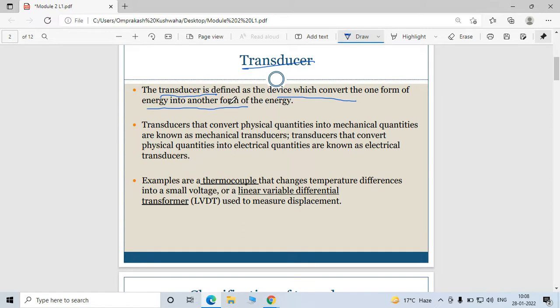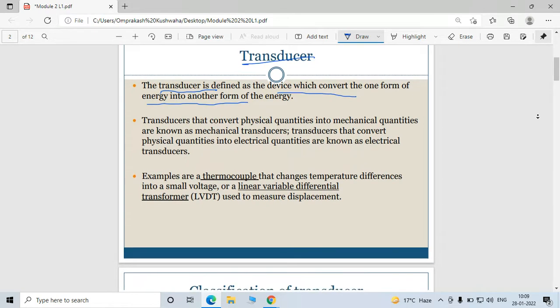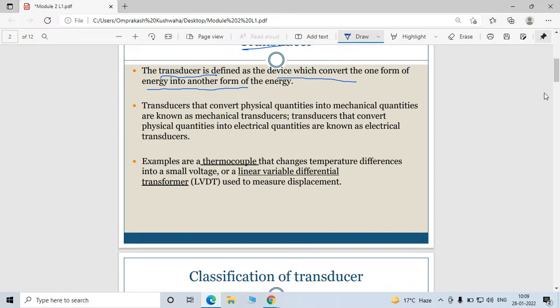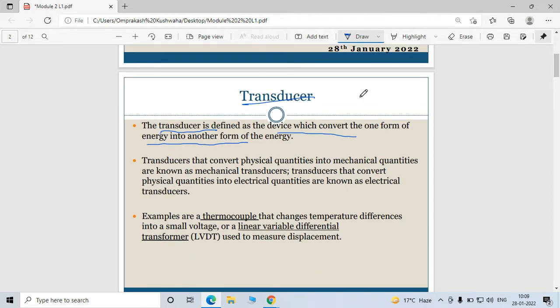The principle on which they work is that the quantity responsible for the deflection is the current, right? The input quantity is current. In the end, that current is converted into a force, and the force is responsible for the deflection angle theta. So in electrical measurement, we measure the electrical input in the form of different scales.